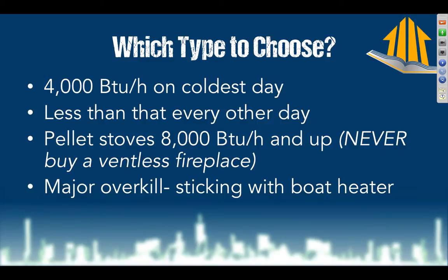So I am not going to do a fireplace, especially not a ventless fireplace, because, by the way, those produce carbon monoxide, period. They do. And the dirtier they get, the more dust gets on the burners, the more carbon monoxide they'll produce. So in such a tiny space, you do not want any carbon monoxide. So do not do that, period.